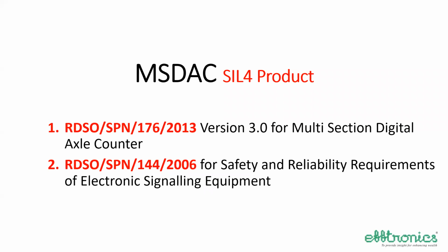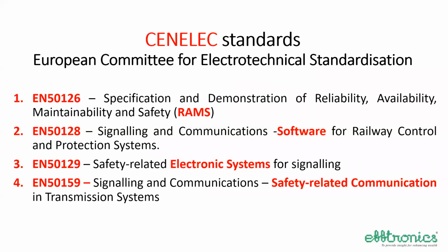Like SSDAC, MSDAC is also a SIL4 product. There is RDSO specification 176. And also for all electronic equipment, there is specification 144, which talks about the safety and reliability requirements, made exclusively for the Indian Railways by RDSO. But generally, all the MSDACs adhere to the CENELEC-like standards.